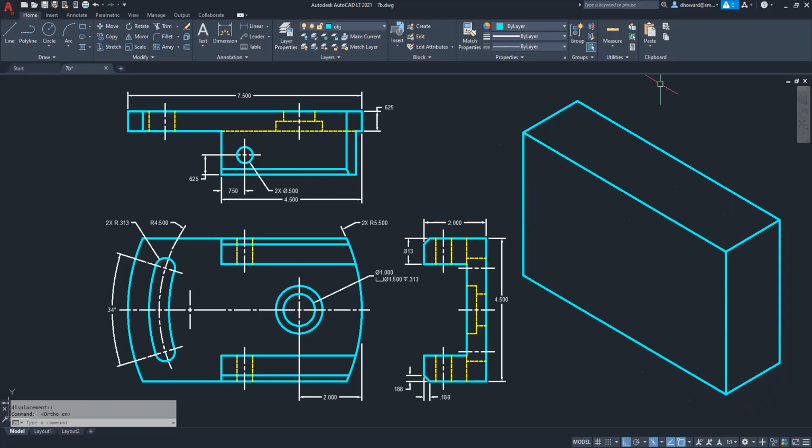All right. So I've got my box, and I already have my center line located here, and maybe I'll use a center line to mark that, just for fun. Check it out. I'm going to go to the midpoint of this one. I suppose I could have just snapped on the midpoint of that line rather than making two pieces. I don't know. I wasn't thinking. Or maybe I was thinking too much. I was trying to be clever. See how I'm snapping to the midpoint of that line? So there you go. I guess that would have been better.